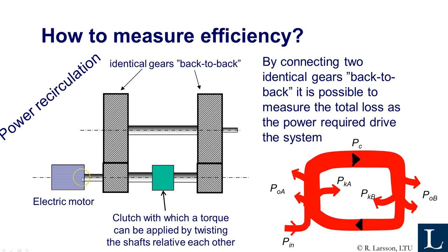and the electric motor here is just there. It gives you the speed, of course, but it also compensates for the losses. So put it like this: the electric motor only needs to compensate for the losses, not more. So you may have 100 kilowatt circulating here, but the electric motor only needs to add 1 or 2 kilowatts. That's the beauty of this machine. You can run very high powers without using very high input power.